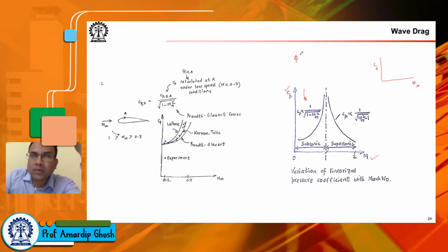But when we bring in this velocity potential formulation for irrotational flow, we apply it for the incompressible flow field. I think a lot of you will be familiar with that, or we will go into the discussion of that when we talk about lift. So we will talk about the velocity potential formulation for irrotational incompressible flow. We will talk about the unit flow fields that can be combined to generate a complicated flow field, flow over a cylinder, flow over a rotating cylinder, etc.